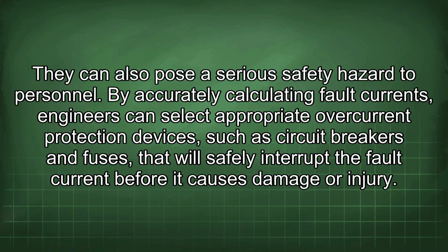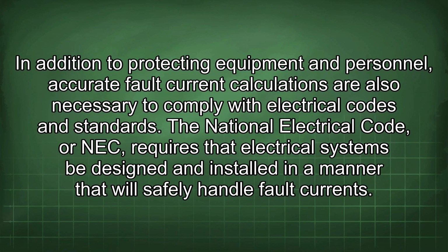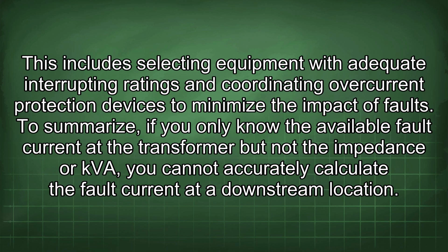By accurately calculating fault currents, engineers can select appropriate overcurrent protection devices, such as circuit breakers and fuses, that will safely interrupt the fault current before it causes damage or injury. In addition to protecting equipment and personnel, accurate fault current calculations are also necessary to comply with electrical codes and standards. The National Electrical Code, or NEC, requires that electrical systems be designed and installed in a manner that will safely handle fault currents. This includes selecting equipment with adequate interrupting ratings and coordinating overcurrent protection devices to minimize the